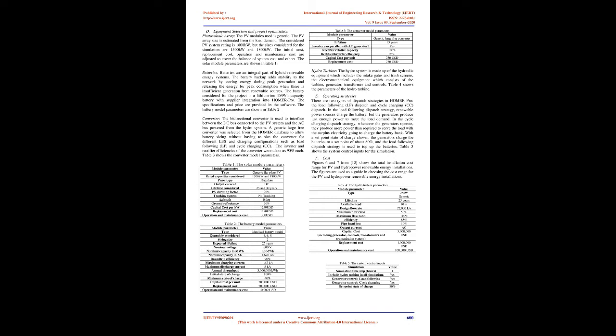According to 9, the hydropower capacity of the Yoke power plant is 3.27 MW. The considerations for this case study are to design a hybrid solar/mini-hydropower system that can supply 3 MW of power to an AC load. The hydropower system is expected to supply a peak power of 2 MW in the rainy season and 1.2 MW in the dry season, leaving enough residual flow for the survival of biota.